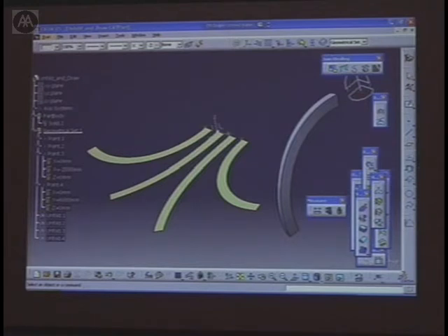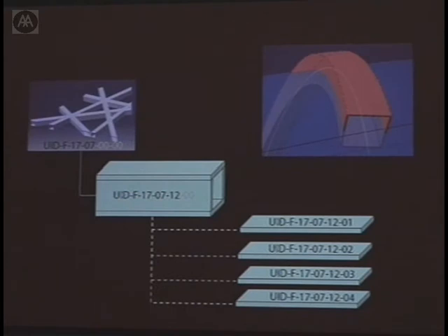You might get some buckling, you might get some warping, or you might have to really curve roll the steel, maybe cold roll it, warm roll it. There's a further deformation going on when you actually weld this stuff through the heating process. So mapping from that to that in real material world terms is not so easy, nor is it to track it. You want to actually be able, in this case for the contractor and the client, to track down every single individual plate that makes every single individual girder that makes every single one of these components.